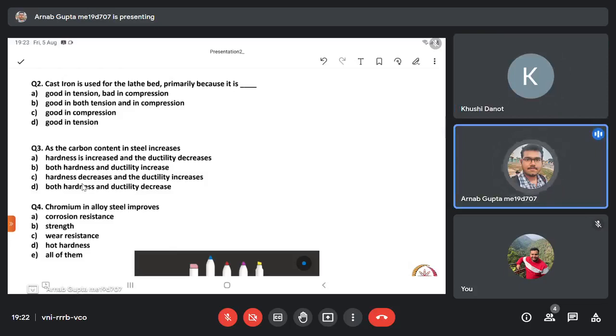Yeah, it's partially correct. Actually, it absorbs the vibration and the jerk that is being produced during machining, and also due to the running of the engine or the power source. So that vibration is partially being absorbed by this bed, and then it is being transferred to the foundation. Foundation is basically that cement, that protruded part over the ground on which we are mounting this lathe machine.